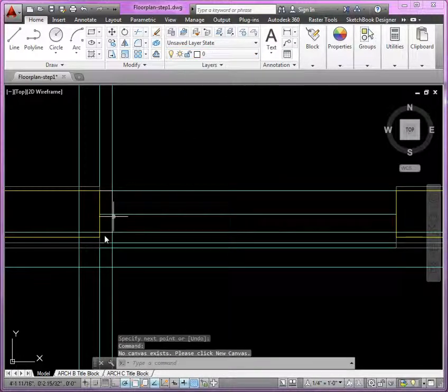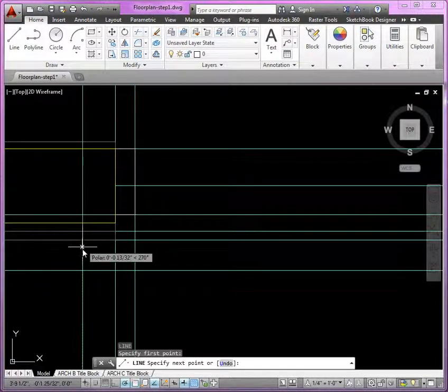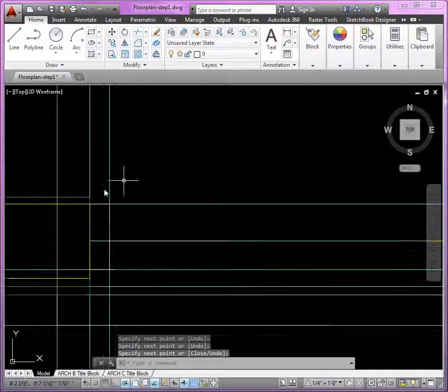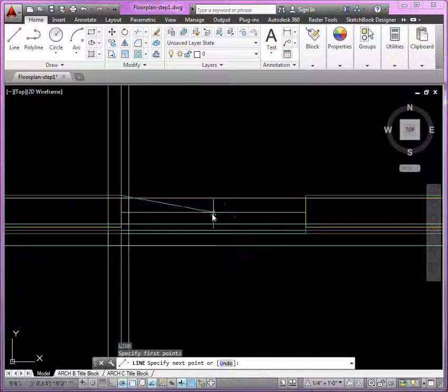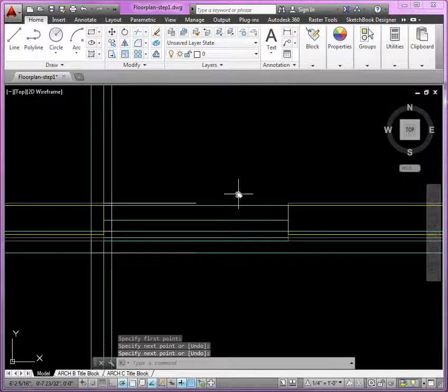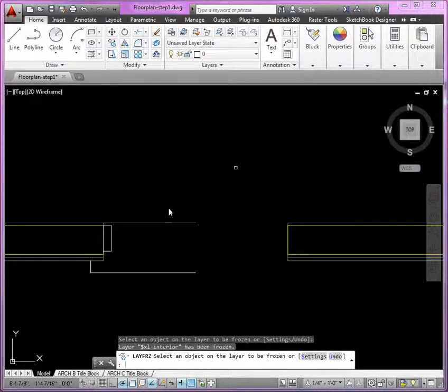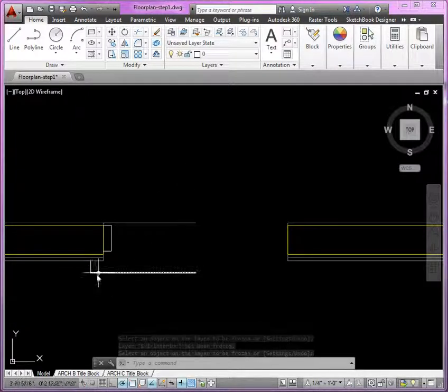Our line work for the sill, you can see, will start out here. So if I go from here to this offset, and then bring it all the way back to the midpoint here, you can see how I can track. Okay, and then if I create the inside here, also all the way to the midpoint to there, I have the line work. Now it may not be visible right now, but here's what I'll do is I'll freeze the construction line layer, and now you can see. Right, so this is one half of the sill line work here.